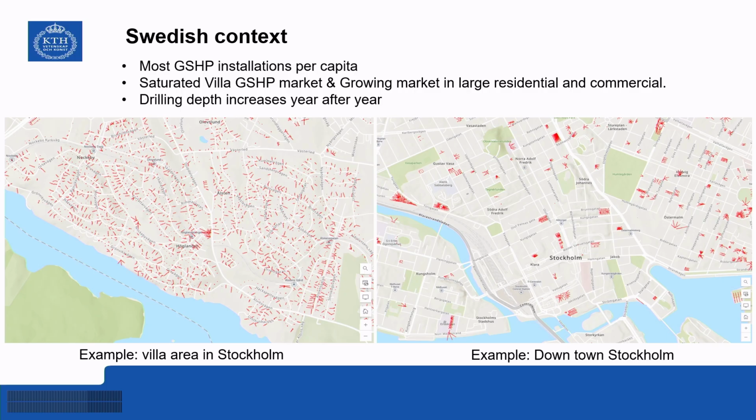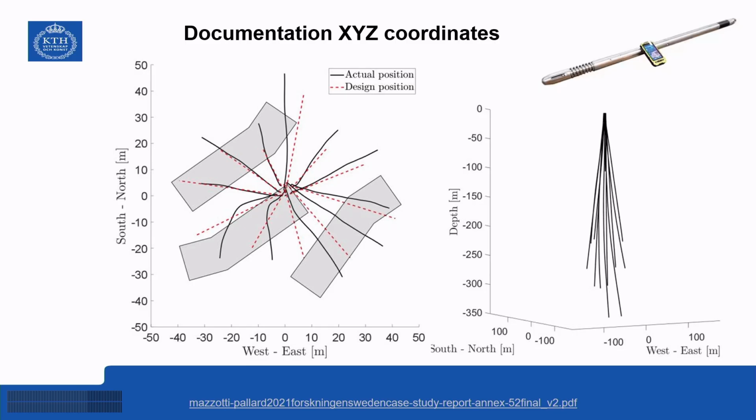And then the question comes to how deep these boreholes are. You see the projection, and we have statistically seen a very clear tendency of increased borehole depth with time. So in the last 40 years, boreholes that were before like 100, 200 meters deep now are 300, 400, even 450 meters deep as a standard depth for all these types of installations.